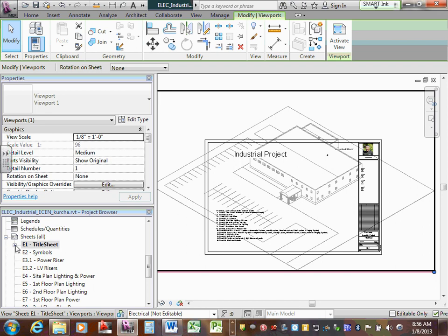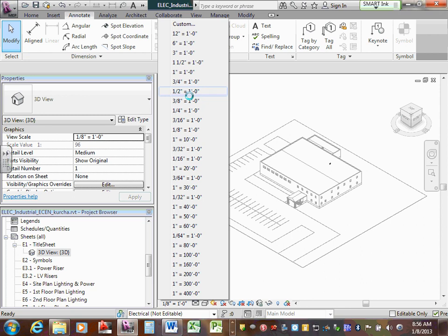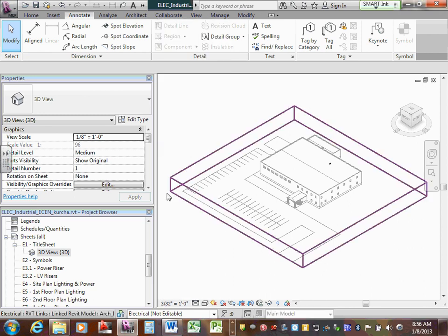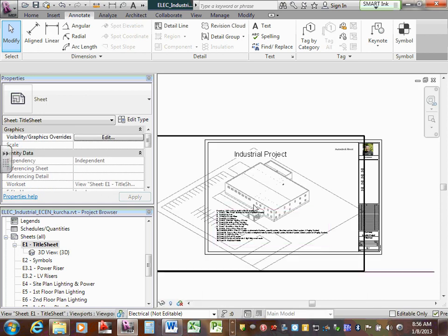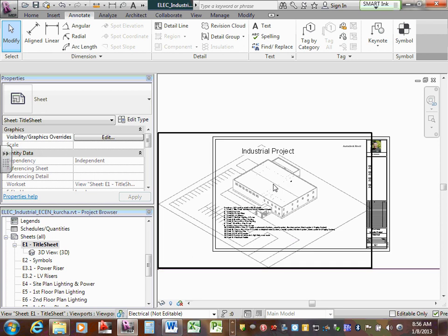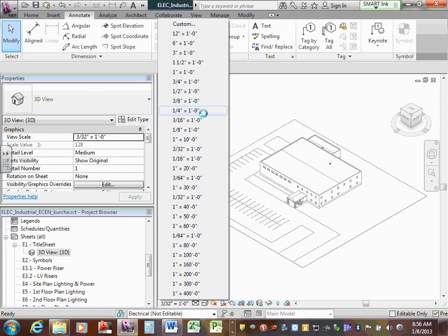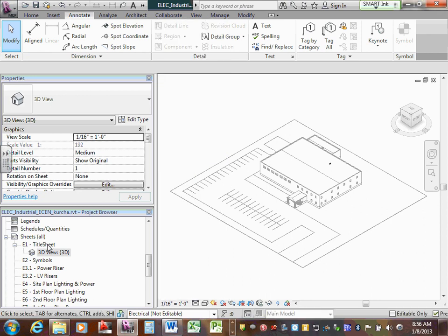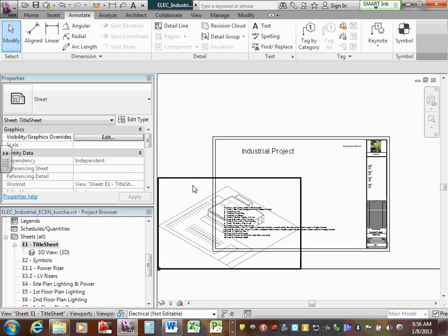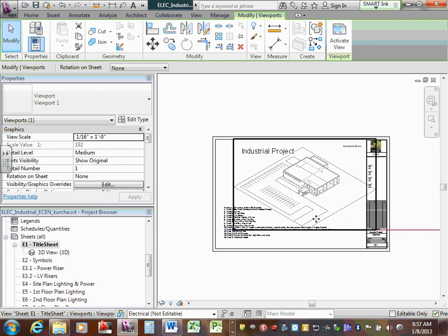So if you click here, here's my view. I'm going to scale my view into a lower scale. Where am I here? 3/16. Let me see how it looks. Almost there, right? A little bit more. Can you guys see how I'm scaling it? It's almost fit. You come over here. See how easy, Gary? Right here is the scale. I did 3/16. I'm going to go 1/16 here. And here's my view getting almost close to fit, right? Can you guys see that?